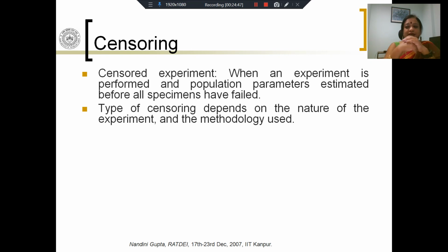And that leads us to believe that those breakdowns are not happening because of the breakdown strength of the material, but because there might be partial discharges at the edge, stress intensification at the edge, which is not a material property, but rather an artifact of the insulation and electrode assembly. So if we use those experimental values to estimate the breakdown strength, we will get a much lower value than is true.